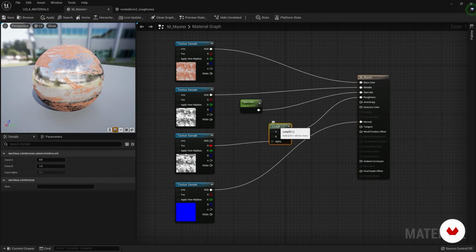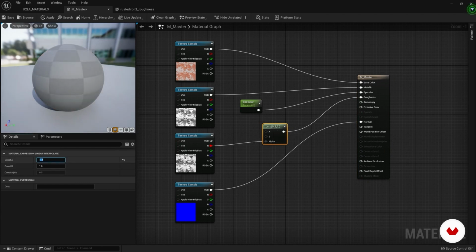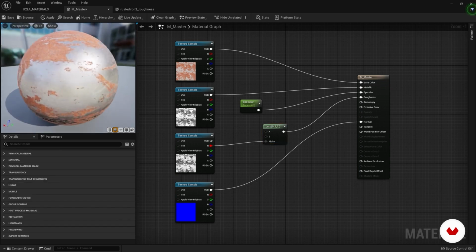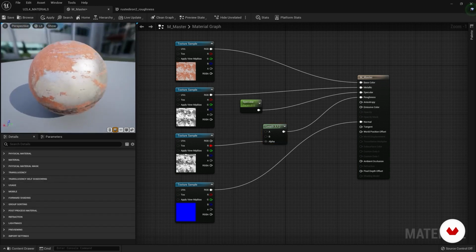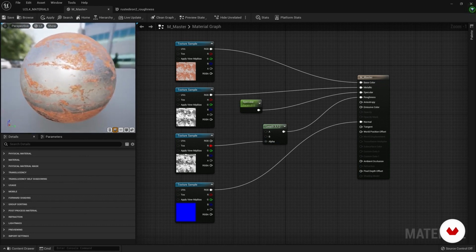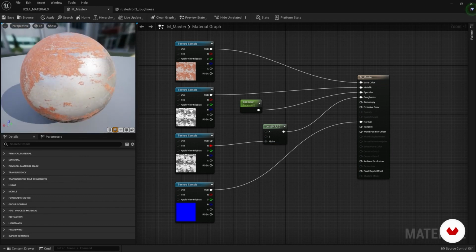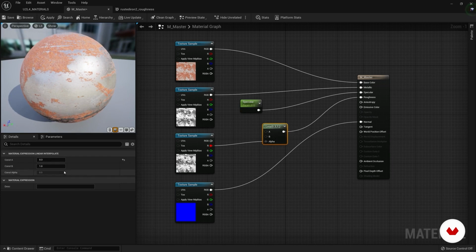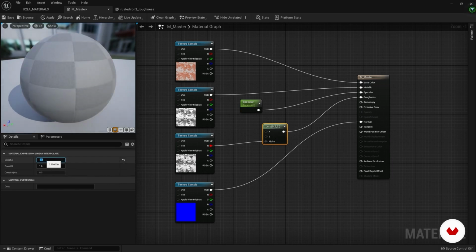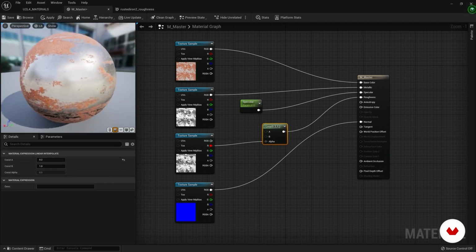Normally, when we use a roughness map, it is good to create a limit to the minimum value, usually 0.3. In addition to giving a more realistic image, the type of material in the part where it was more reflective has really changed. By acting on this parameter, we can customize the behavior of the reflection.